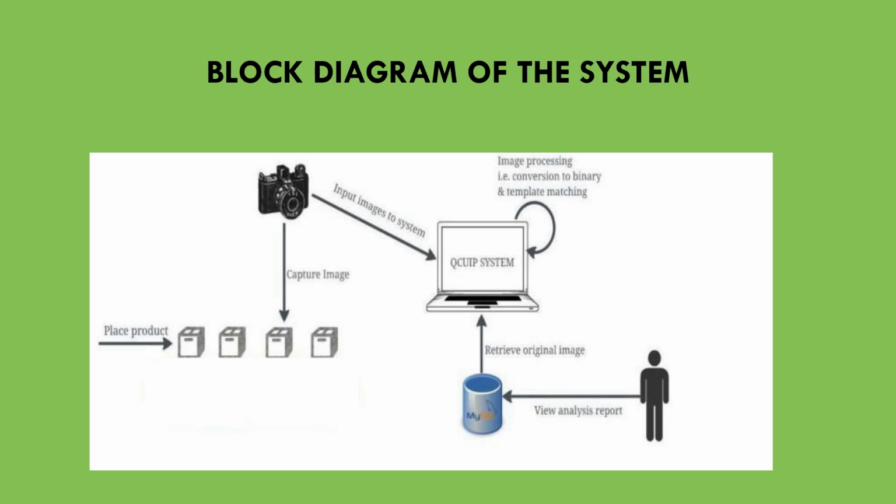The binary image is given as an input for the template matching process. This image is compared pixel by pixel with the template image of an ideal product to verify the actual shape and dimension. Matches are estimated based on the intensity values of both image and template. If the templates match accurately, then the product will be considered as a non-faulty piece.